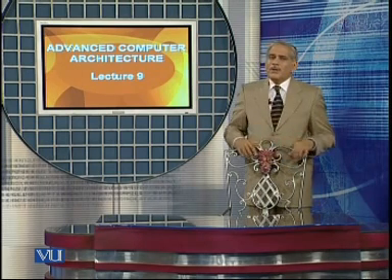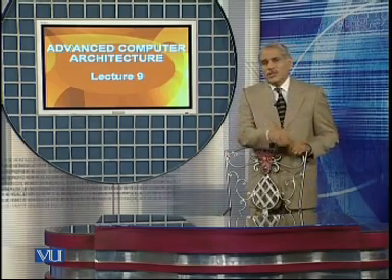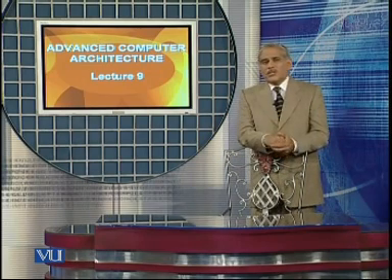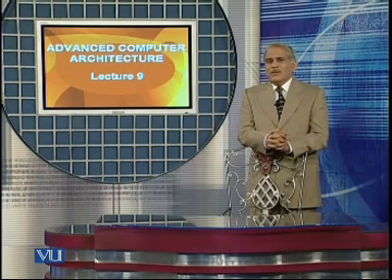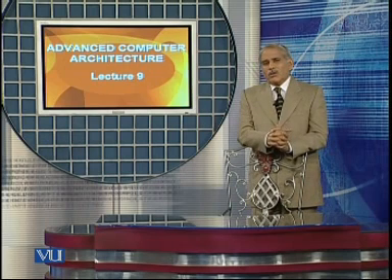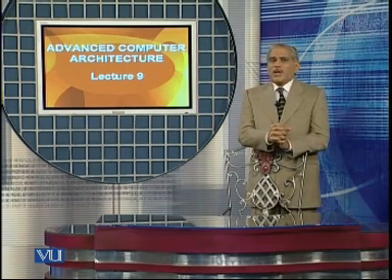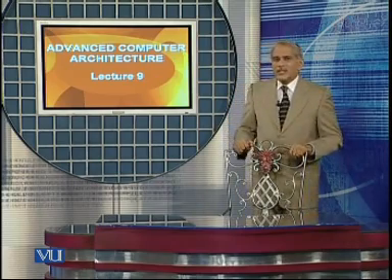For example, during the first clock cycle, we can perform the instruction fetch. During the second clock cycle, we can perform instruction decode operation and the register read operation. Similarly, during the third clock cycle, we can perform the execute, which depends upon the type of instruction, and it also determines the next step.